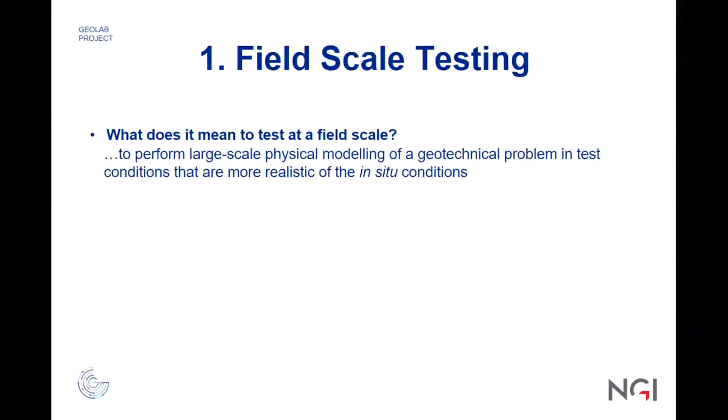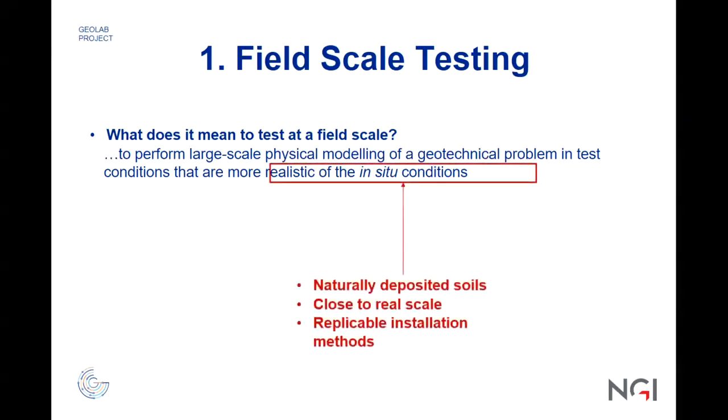Now, what does it mean to test at a field scale? As standard, it means to perform a large-scale physical modeling of a geotechnical problem in test conditions that are more realistic of the in-situ conditions. What that really means is that we test in naturally deposited soil, as opposed to what you've seen all day, where the sand is prepared. It is done in the real operational environment.